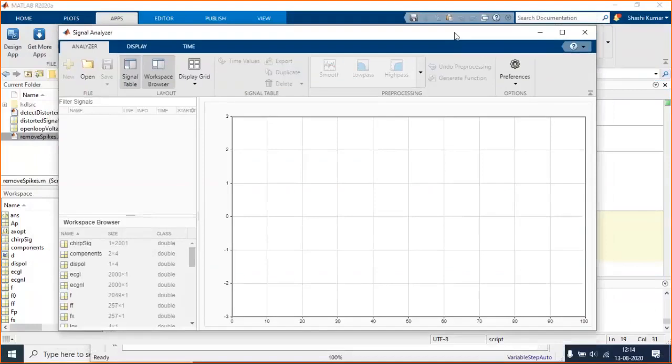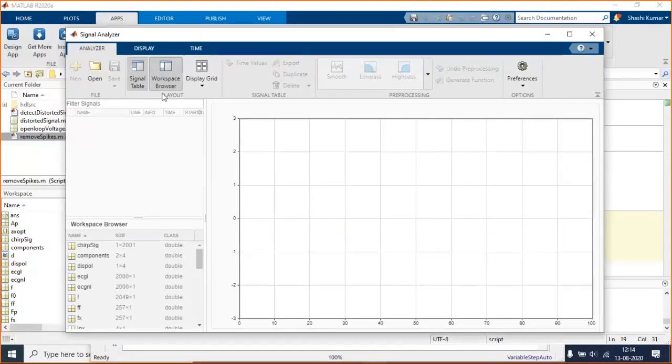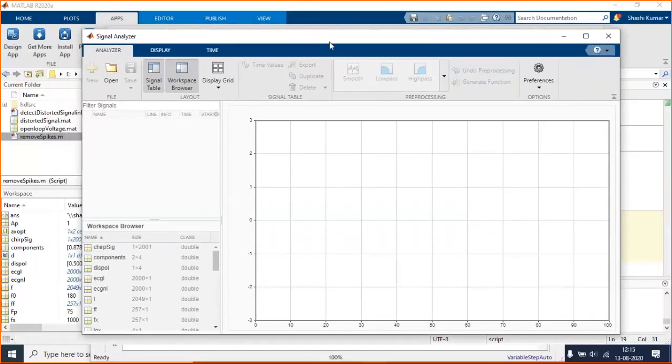Yeah, so I've been using FFT in my previous company, where I was a biomedical engineer developing medical equipment. There we usually handled very low frequency signals. For medical devices the order is very low, or the sampling frequency itself is low, so they work with 256 or 512 or 1024 points. The maximum they go up to is 2 kilohertz or 5 kilohertz, because the ECG and EEG signals we acquire have their major frequency spectrum at around 1 to 5 hertz, right? So that is one application.